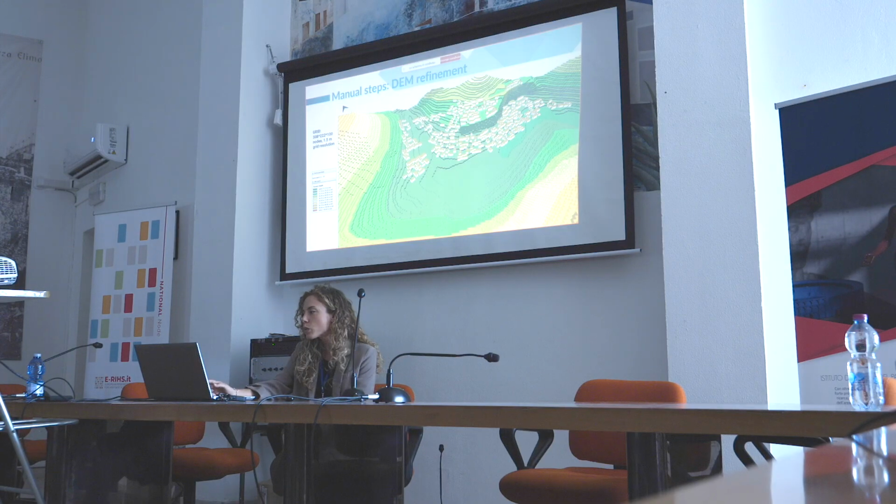Thanks to this procedure, it was possible to export the final file in the format ready to be executed in ENVI-met, which you can see here directly inside the software. And we also manually refined the digital elevation model, which was slightly interpolated in the US database system, to better represent the very steep separation between the upper center of the town and the rest of the village on this side.